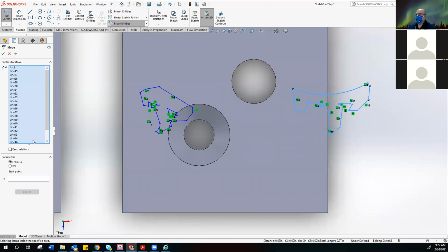Okay. Now, what you want to look at here at the bottom of that list is a box that says keep relationships. What that allows you to do is, if you leave something behind, it will still grab anything you missed and pull it with it, but it'll leave the part you didn't select that's not connected. So you might have a string on it thing happen. You can go ahead and turn that on for this because you should be able to get everything. It'll also help it from making a mistake on there.